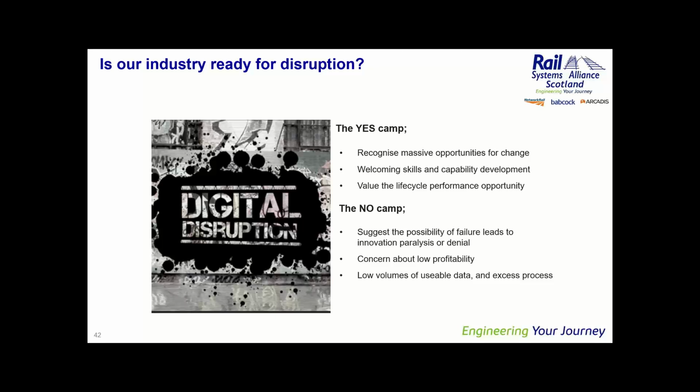They can start to pre-order new parts before they reach the stage of failure. And, you know, facilities management in a lot of industry has been all about operate to failure and then replace. And that then might introduce a period of wait while you order parts and all that sort of stuff. And that's where the BIM model, the asset information model, not the BIM model, the AIM.